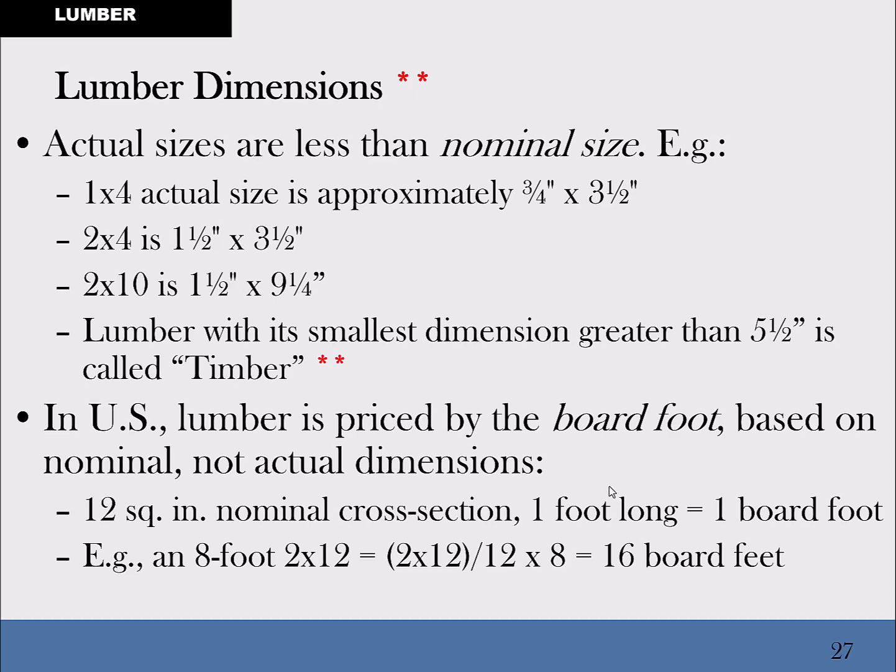Every square foot of hardwood flooring you put on the floor would be considered a board foot. But if your hardwood floor is more than 1 inch, it gets rounded up to the 2-inch number. And so every square foot will be 2 board feet. So if your board is 1 inch or less, then every square foot is 1 board foot. That's the simplest way to describe it.